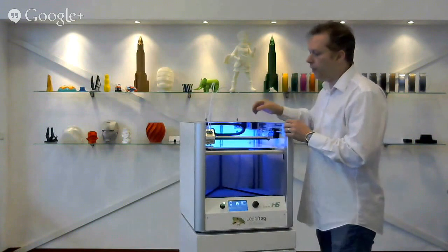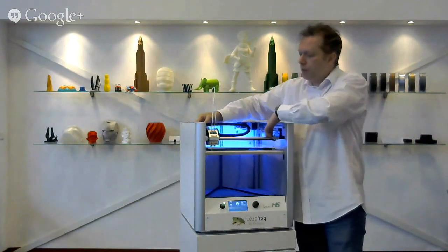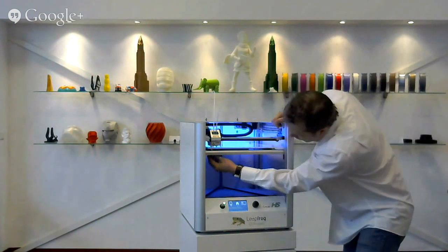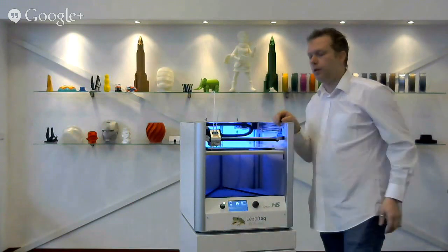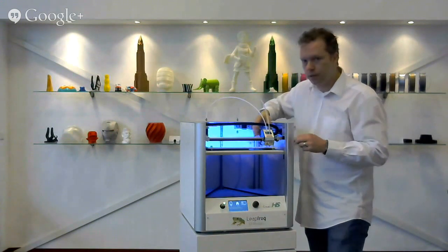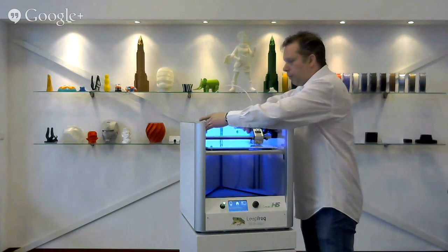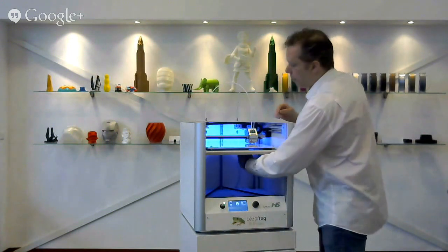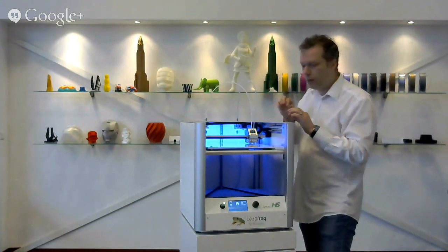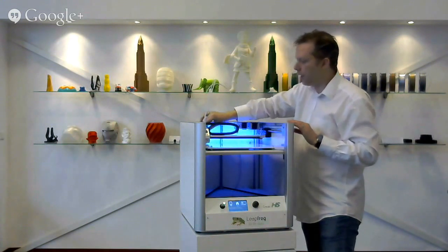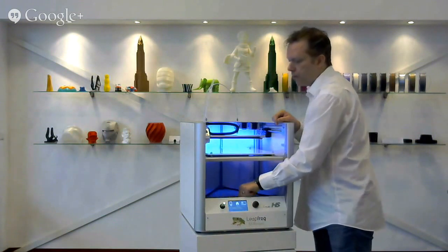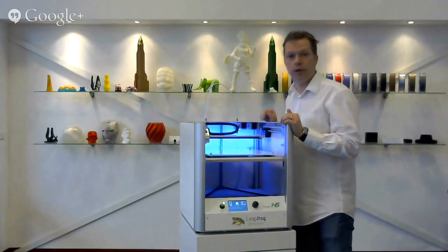After you found that exact point, you can gently move your printer head forwards, all the way to the right. And now you can adjust with the knobs underneath the level of the bed compared to your nozzle. You can gently move your head to the other side, do it again, move it all the way back, then again, the rear knob you can adjust, and you can fix that exact point where the nozzle is just barely touching the bed, also to the other side, and once you're done, then you're level. So that's how to level your printer bed without hooking it up to a PC.